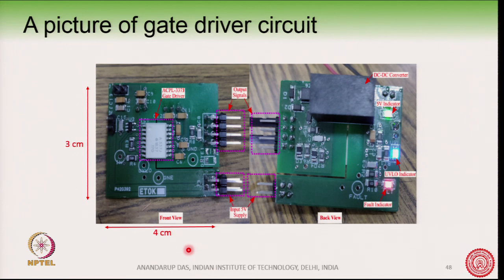This gate driver board has many protection features, as this driver IC also provides us with that. It also has an isolated DC-DC converter, and there is also a cut on the PCB so as to provide a physical isolation. We have been using this gate driver board to drive the SiC MOSFETs, but it can also be used for driving IGBTs or silicon MOSFETs.